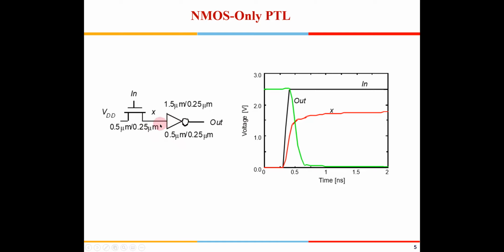We'll see that it depends on the functions, right? You can use 2 inverters. You don't have to make a domino logic and all, because when we are talking about domino logic, then we are moving into dynamic logic where there is a clock and all. So here, if you don't want an inverting output, then you can use 2 set of inverters, or you can implement the invert function here itself, right?